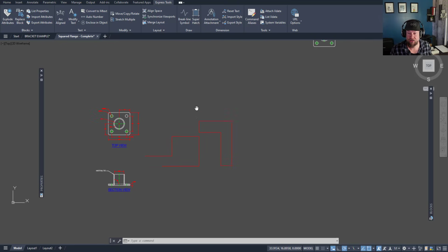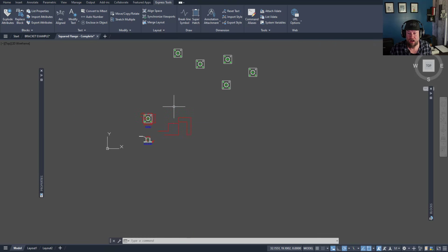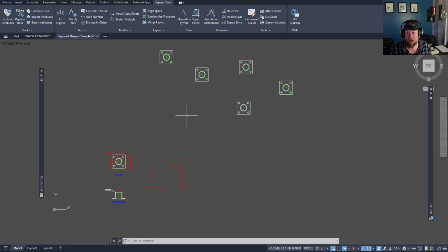Next up is another set of commands that you're definitely going to want to memorize, and that is the zooming around and moving within AutoCAD. Now, I'm zooming in and out using my middle mouse wheel. You can also click down your wheel and pan around the drawing. That's great for many users and most of the time,